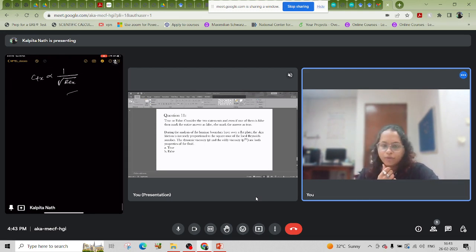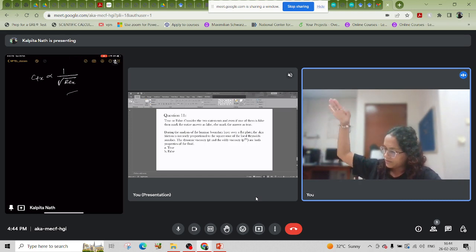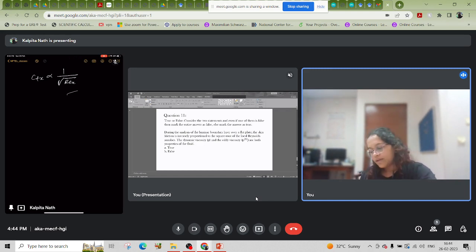So the first one is true, but for the eddy viscosity, in case the dynamic viscosity and eddy viscosity are both properties of fluid. No, the eddy viscosity is a coefficient that is relating average shear stress within a turbulent flow of water or air to the vertical gradient of velocity. The eddy viscosity depends on the fluid density and the distance from the river bed or the ground surface. Eddy viscosity is primarily decided by the conditions of the flow. But dynamic viscosity is the property of the fluid. So eddy viscosity is not the property of fluid. So that's why this answer is false.